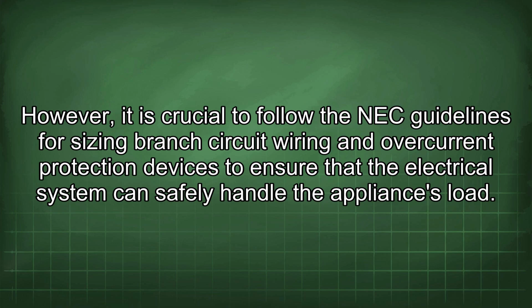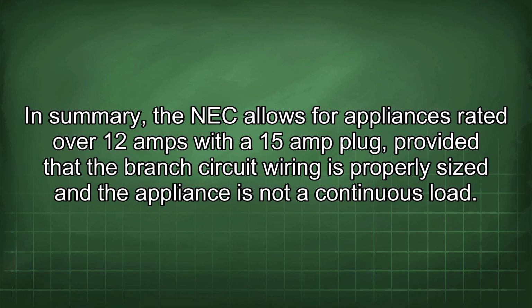However, it is crucial to follow the NEC guidelines for sizing branch circuit wiring and overcurrent protection devices to ensure that the electrical system can safely handle the appliance's load. In summary, the NEC allows for appliances rated over 12 amps with a 15 amp plug, provided that the branch circuit wiring is properly sized and the appliance is not a continuous load.